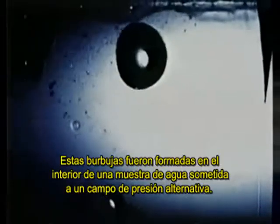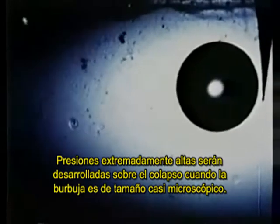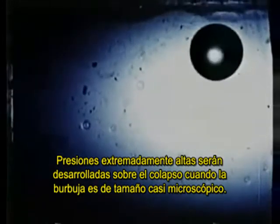These bubbles were formed in the interior of a water sample subjected to an alternating pressure field. If such cavitation bubbles remain spherical throughout their life history, extremely high pressures would be developed upon collapse when the bubble is almost microscopic in size. Estimates indicate the pressure produced near the position of minimum radius is of the order of thousands of atmospheres.